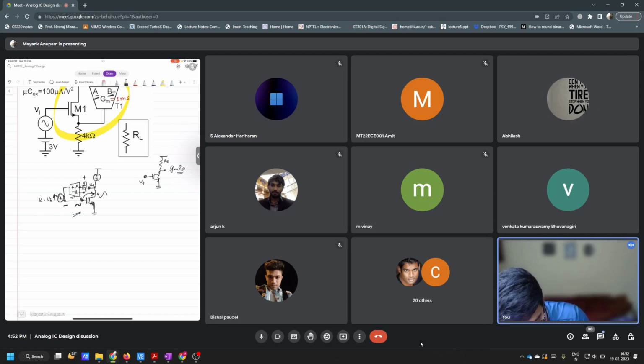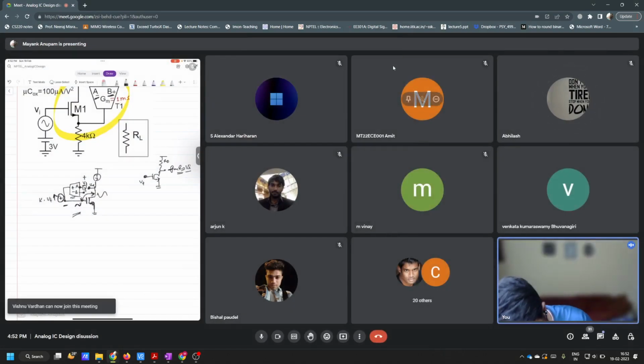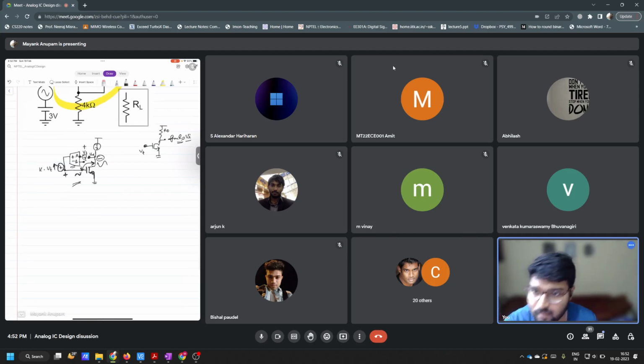So this is minus Gm times Rd times Vi, right? There's a minus sign here. Yes, so this is inverted, isn't it? If this is plus here, then this will be minus here, right? So you see that the sign that we chose first was right. But this is indeed plus and this is indeed minus, because when we apply a test voltage in this configuration of plus and minus, the return voltage is negative of what was applied, isn't it?